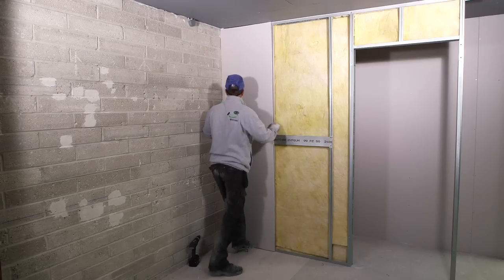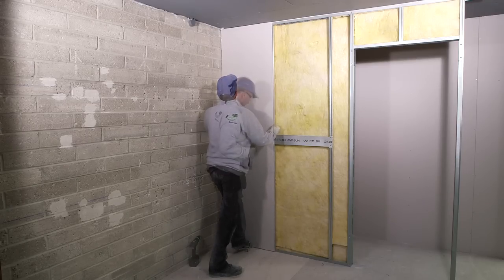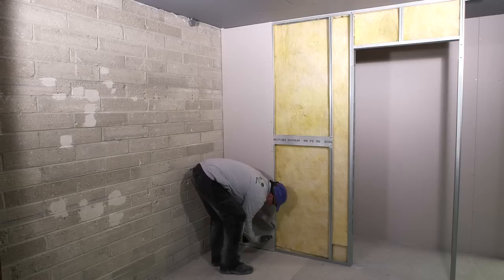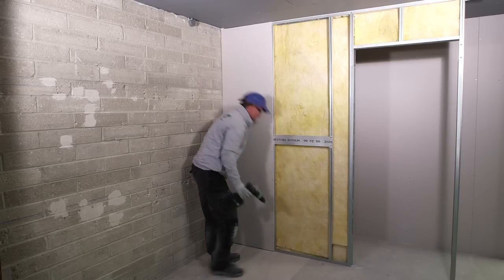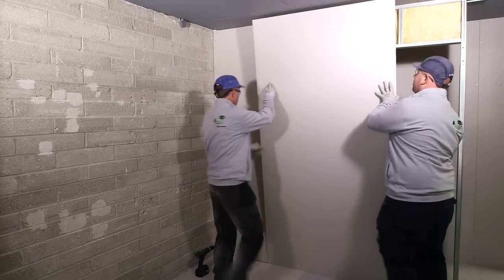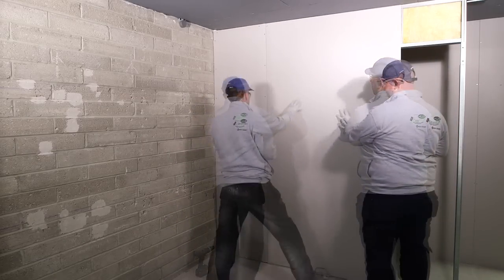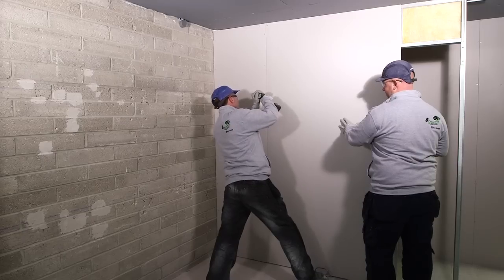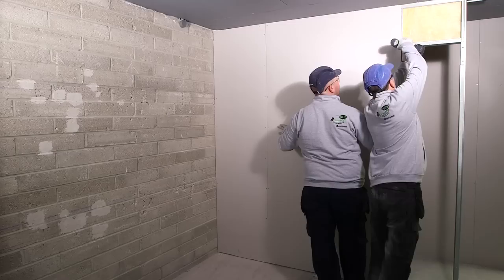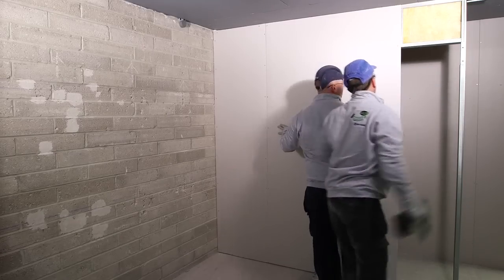Gyproc plasterboard joints are staggered on either side of the partition by 600mm, so when you start boarding with a full board width of Gyproc plasterboard, this will be staggered by starting with a 600mm wide Gyproc wallboard on the opposite side. Gyproc plasterboards are fixed at 300mm centres, with the appropriate length of Gyproc drywall screw. At external angles, reduce fixings to 200mm centres.